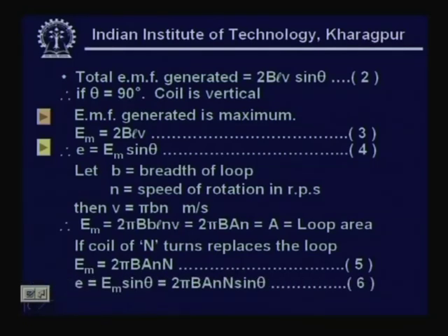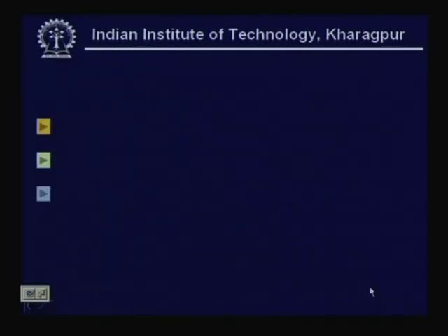That being the case, one arrives at the equation e = Em sin θ. So, this tells us that the voltage generated is sinusoidal in nature with a magnitude of Em. This is the essence of single phase generation. Now, what is a three phase generation? Let us see.